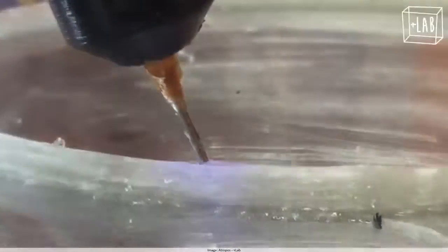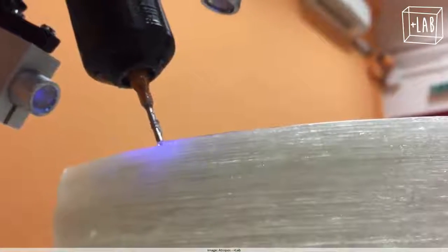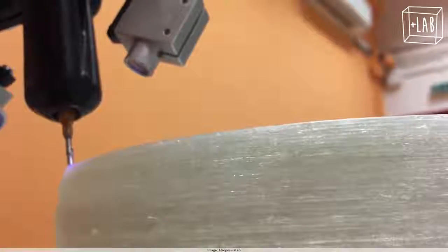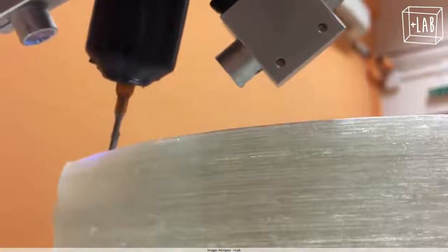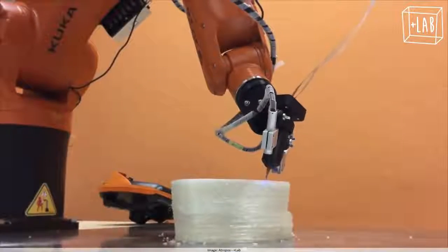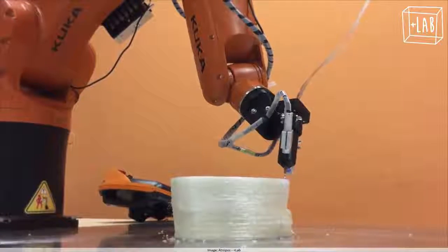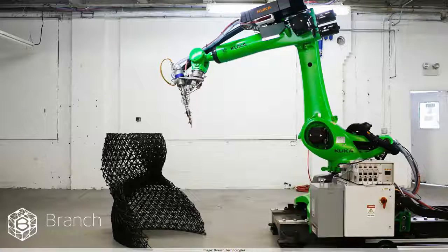So they didn't want to melt plastic, but they actually extrude fiber that has been put through resin, and then the blue light that you're seeing is UV light that's used to harden it. And if you want to do something like that, it's not enough just to take your standard 3D printing software and use the G-code from that one, but you see that it actually has to tilt the tool. So you need to define a strategy for how you can extrude that in an efficient manner with a new process.